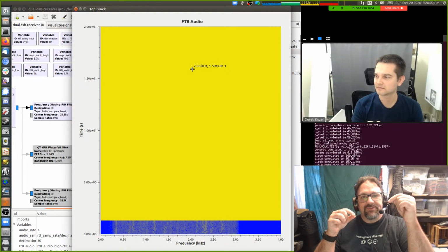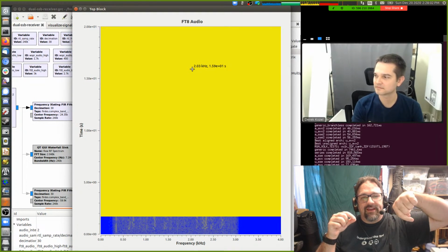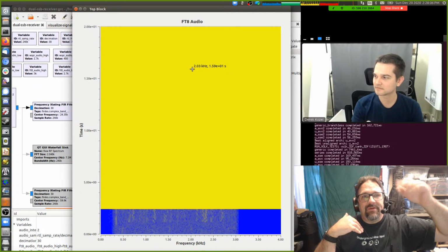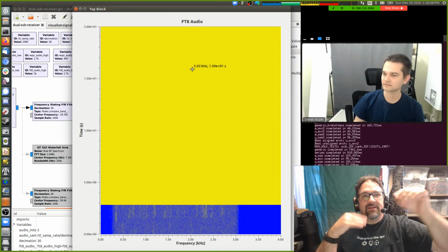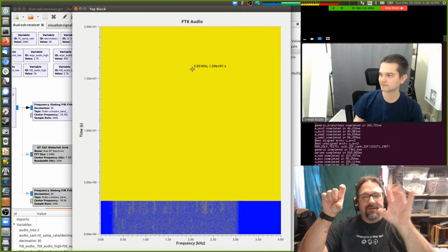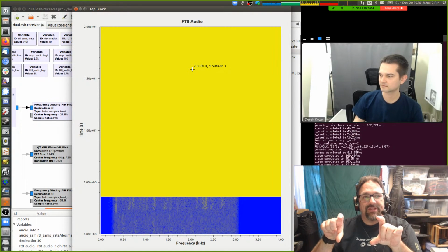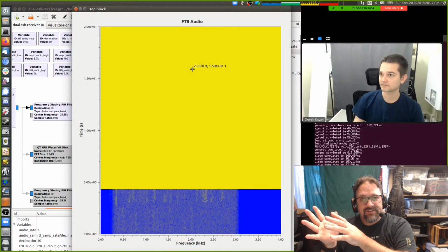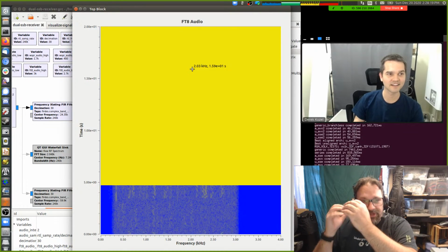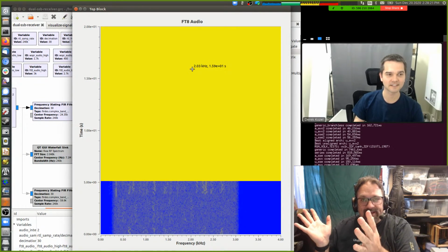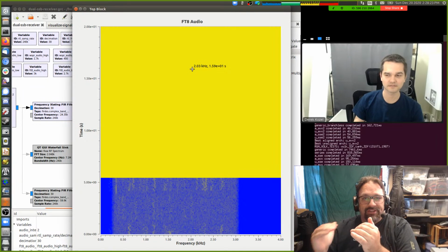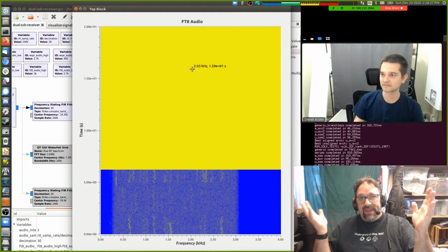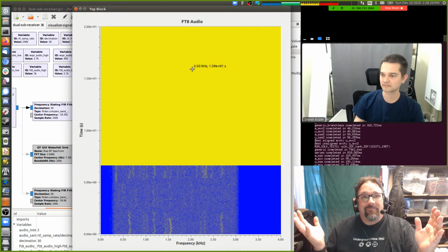To have a wideband receive antenna come in and go to these two triplexers. The input to the triplexer has another output, just in parallel with it, so you can cascade multiples of them. And so the idea is to have one wideband receiver come in, go to 3 different bands on one triplexer, another 3 bands on the other triplexer, take the outputs of these into their own RTLs and into GNU Radio to split out all of these bands and run a bunch of WSJT-Xs to receive all of this, potentially on 6 bands concurrently, right?